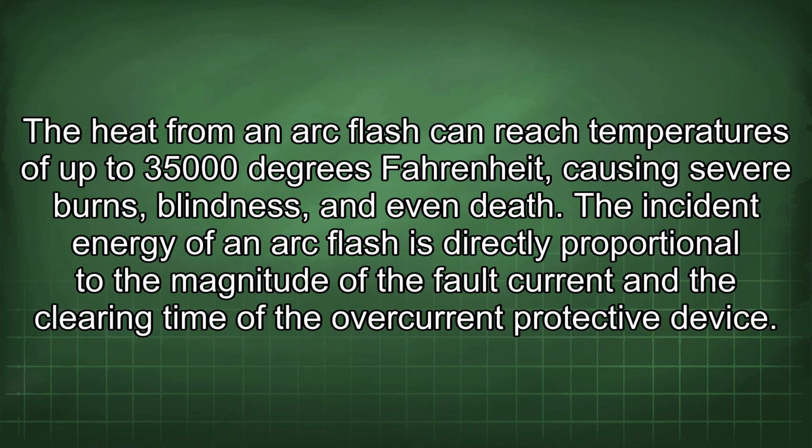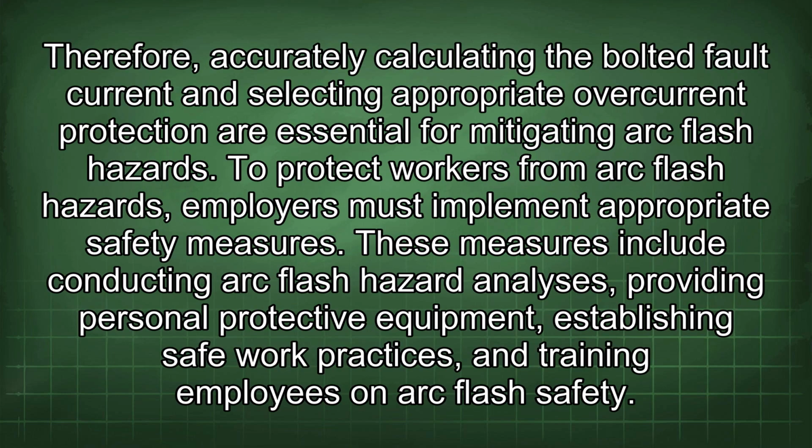The heat from an arc flash can reach temperatures of up to 35,000 degrees Fahrenheit, causing severe burns, blindness, and even death. The incident energy of an arc flash is directly proportional to the magnitude of the fault current and the clearing time of the overcurrent protective device. Therefore, accurately calculating the bolted fault current and selecting appropriate overcurrent protection are essential for mitigating arc flash hazards.